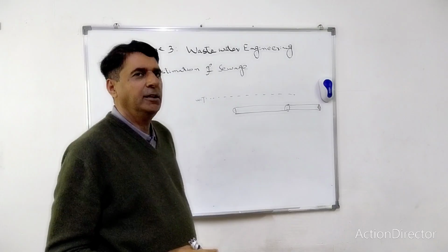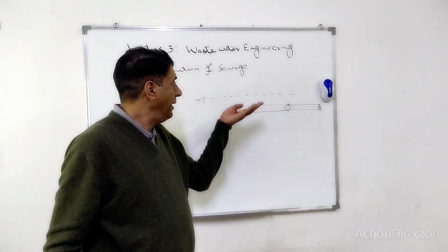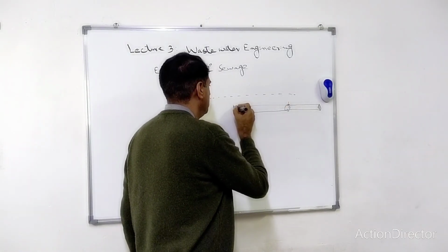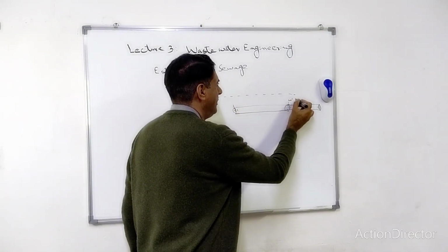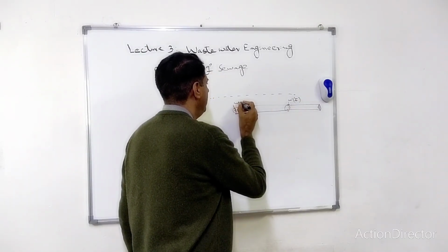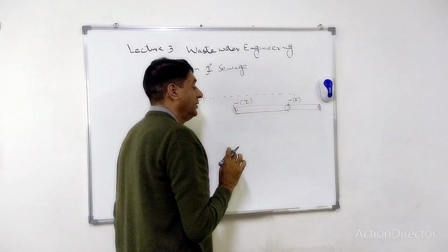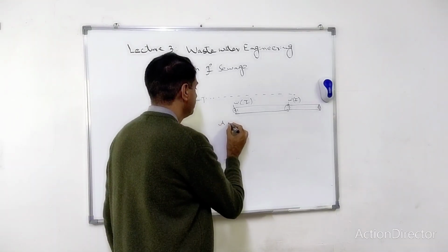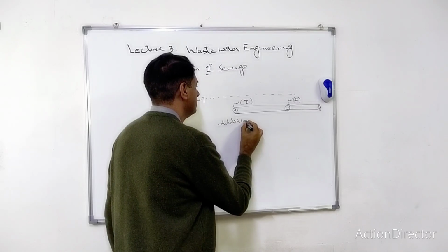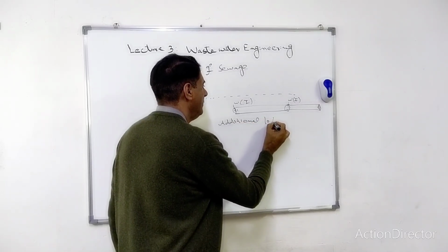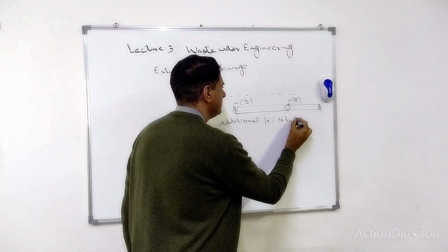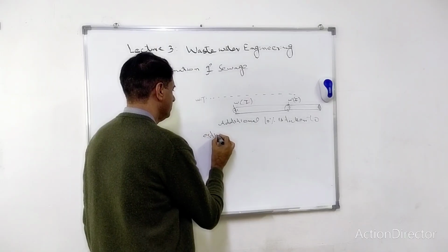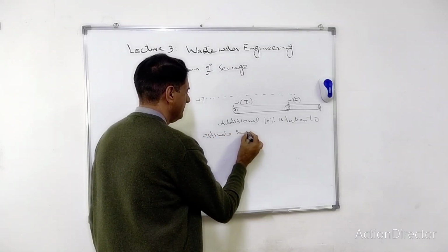In this situation, the groundwater can enter the pipe through the joint, if the joints are weak. This water is known as the inflow or infiltration. In this case, an additional 10% is taken to estimate the sewage.